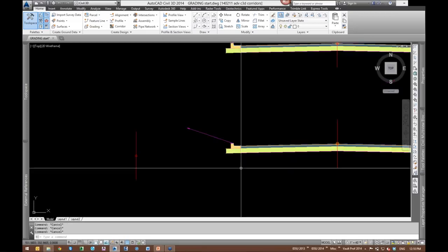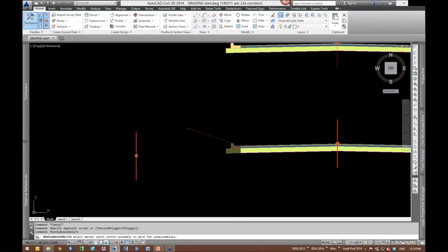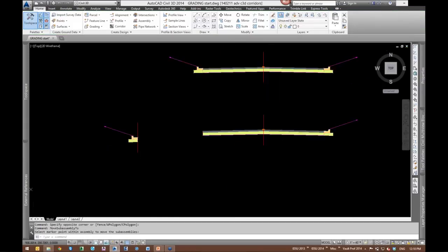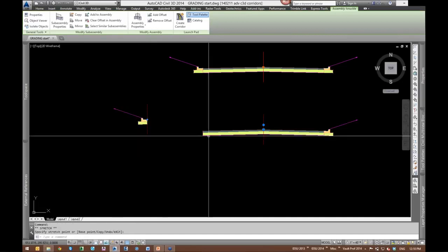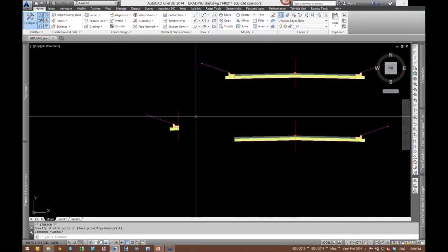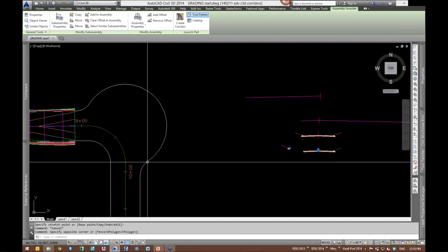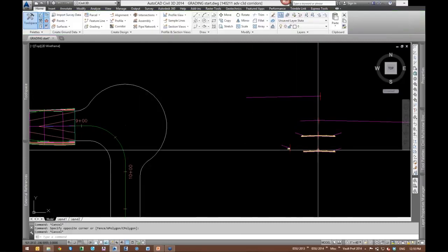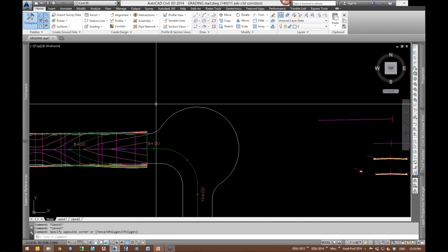And what we're going to do is take this curb and this daylight sub-assemblies, and move that over there. Now the location of this assembly offset, its proximity to here, makes no difference. This one is going to ride along an alignment that goes along the knuckle here. This assembly will ride right along here. So let's look at how that's going to work.